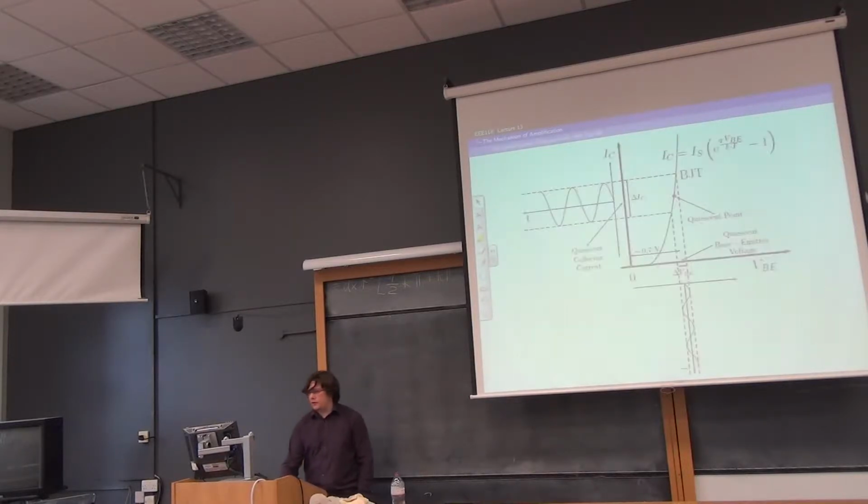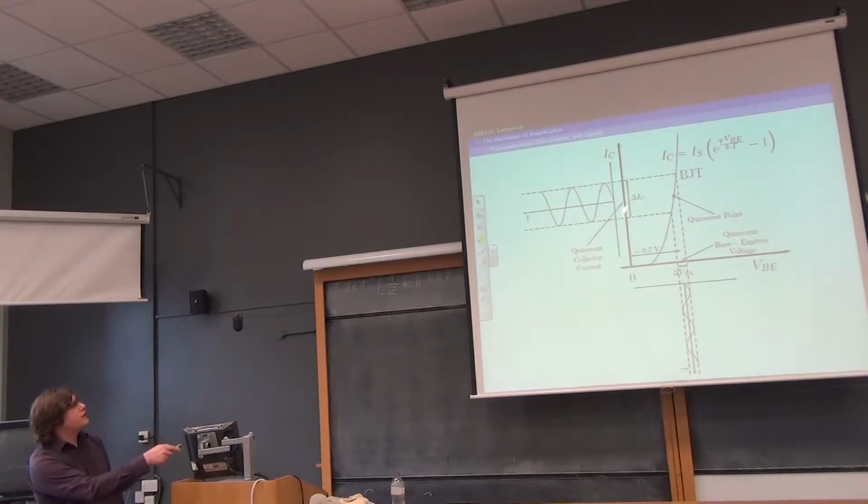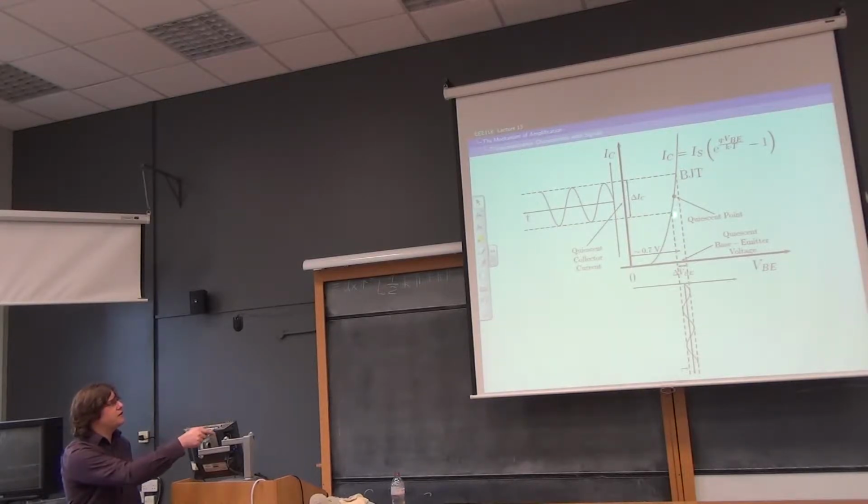That's to say, if I go back to this graph and I said I'm going to divide that distance there by that distance there, I'll get a value for transconductance, that's to say amps out, volts in. And if I'm saying that this line is linear, I should get one value to completely describe that line, because it will be the gradient of that line.